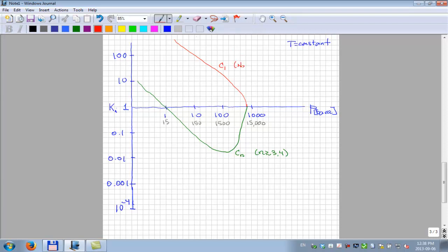It'll look similar also. Nitrogen will look like that. C2 will look a little bit like that. Maybe H2S. But both CO2 and H2S could go below 1 and come up again. But typically methane, ethane, and nitrogen will all be monotonically decreasing as you go to higher pressures. Whereas all of these heavier components, C3, C4, and so forth, will typically be non-monotonic and have a minimum.